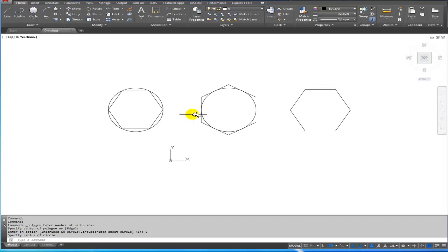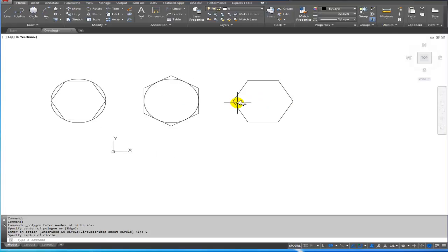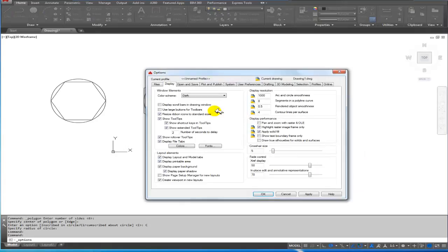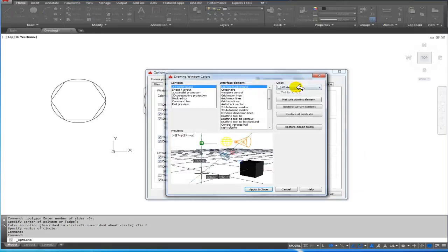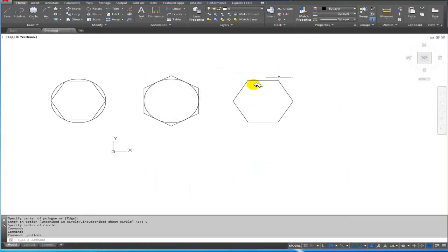Okay. So if I could just do a quick recap of what we did. I showed you how you could change the background, by going right click, options, and then of course colors, and then you could change it that way. I also talked about how you could draw something using these drawing tools. So you always interact with AutoCAD. If you want a line, you say I want a line, and then you say where you want to start the line.